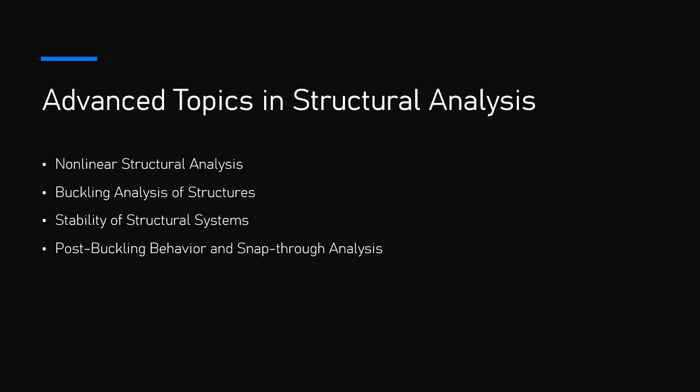4. Impact of buckling on frame systems. In frame structures, the buckling of individual members may not immediately lead to failure. However, buckling failure in one member can cause redistribution of forces within the frame, potentially leading to failure in other parts of the system. Therefore, overall stability and frame stability must be considered in buckling analysis. Buckling is a critical failure mode for slender structural elements, and proper analysis is essential to ensure the safety and stability of structures under compressive loading.